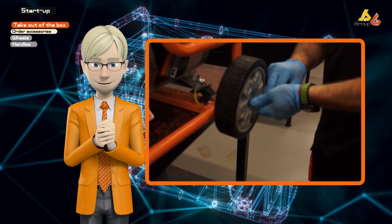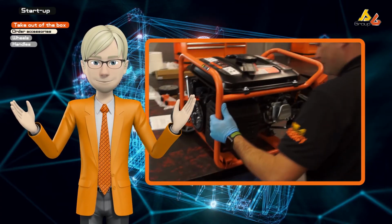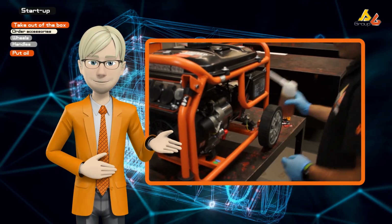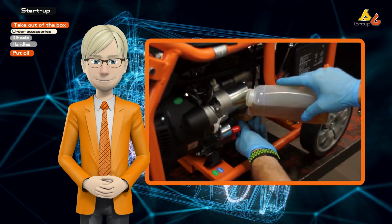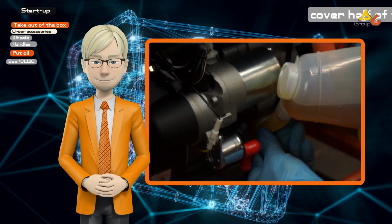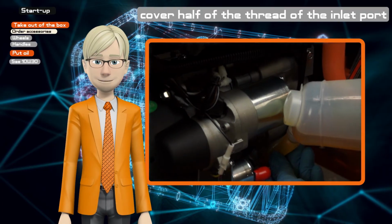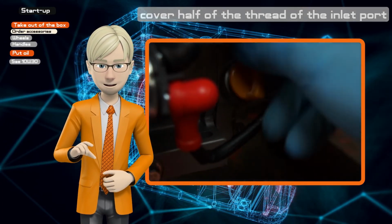Next, we put oil in the engine. How much oil you need is indicated in the manual. This is dependent on the size of the engine. Normally it will be a standard SAE 10W30 oil for gasoline engines. The oil level should cover half of the thread of the inlet port for optimum performance. Both an excess or deficiency in the oil level will not allow it to start or even shut it down preventively.